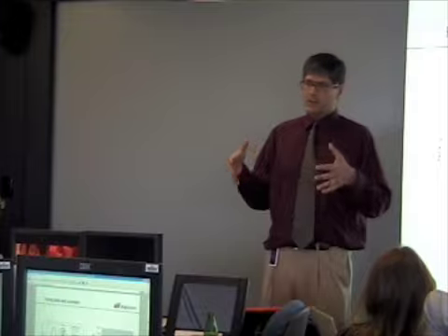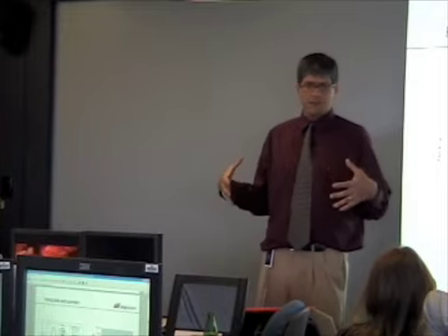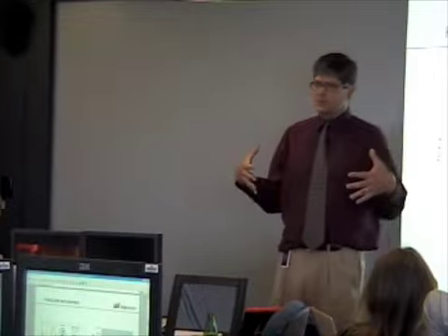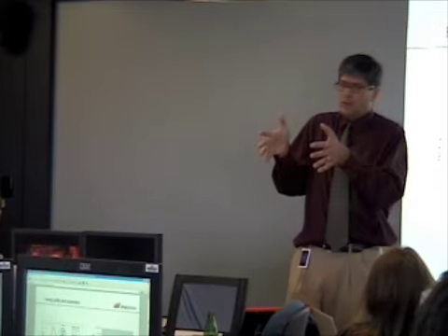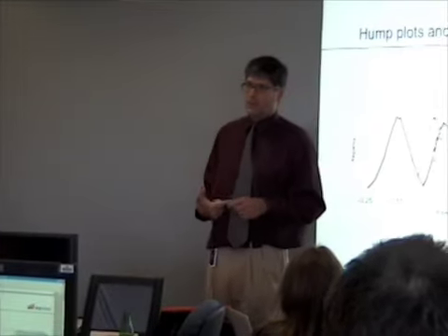When you look at each one of these uncertainties, make sure the uncertainty is big enough to really cover anything. If you err on having the uncertainties too large, you do your sensitivity analysis, and then you ask, what's the important thing, and start using that as your work program, okay?